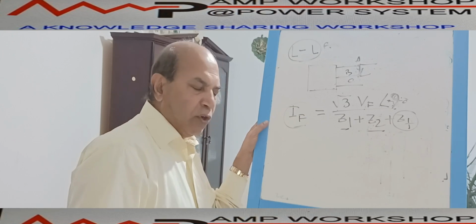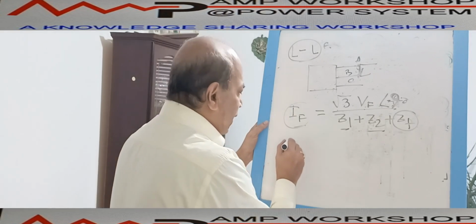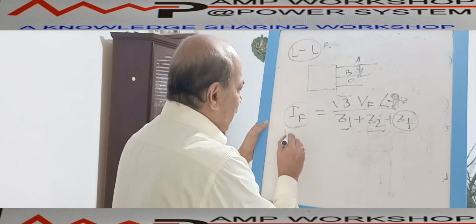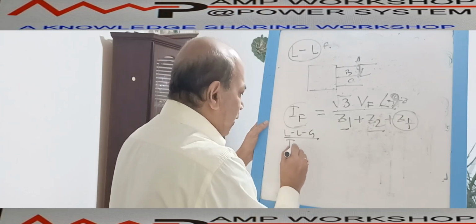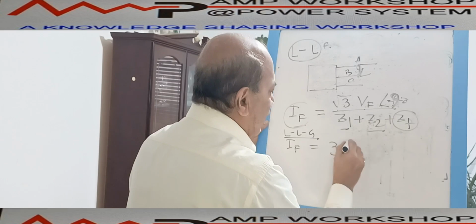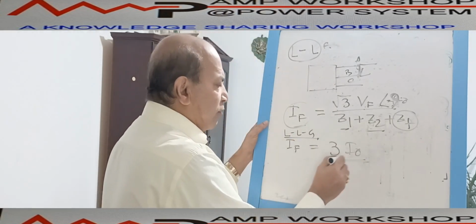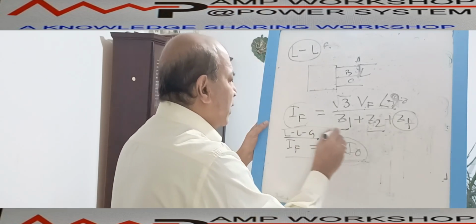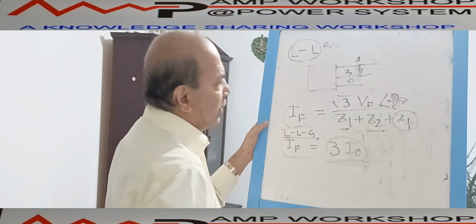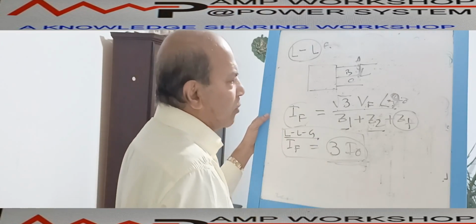In case of double line to ground fault, the fault current will be different. In that case, the fault current in A will be simply 3 times the zero sequence current I0. If we calculate the single line to ground fault current I0, then 3 times I0 equals the fault current in case of line to line to ground fault. So these are the other two relations which we can derive in the same way. But it will take more time to calculate. That's why I am not going to calculate this thing.